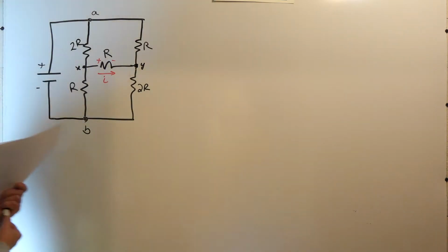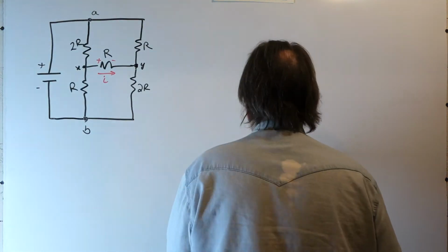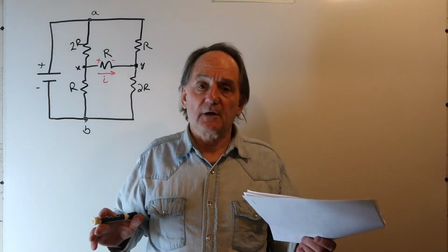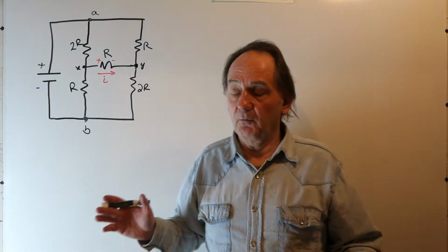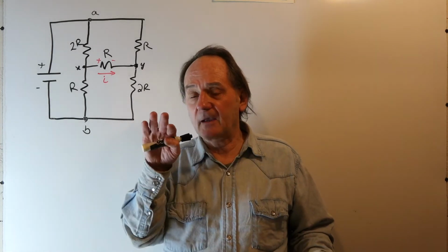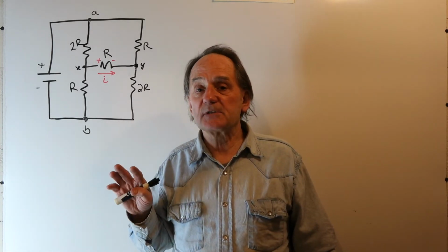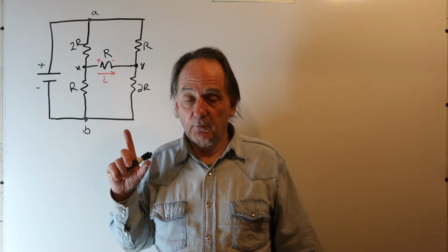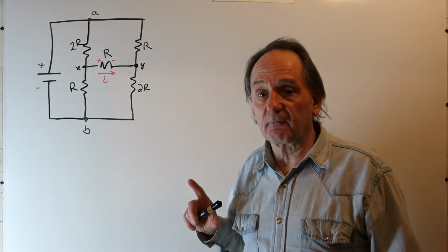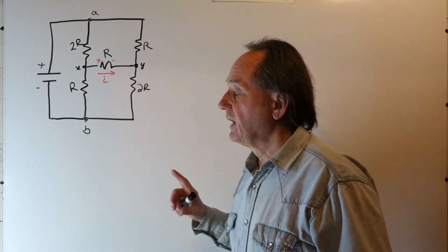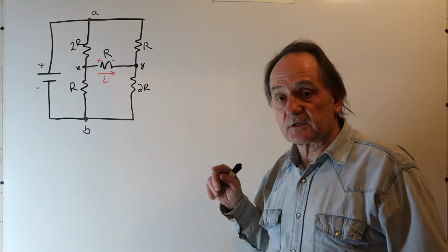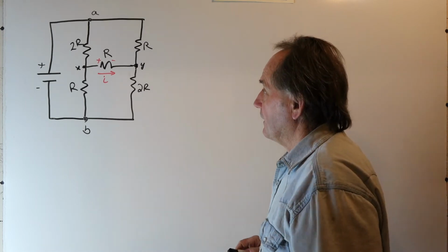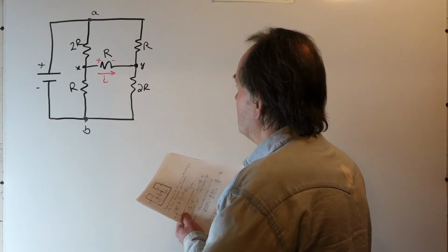Now, a Thevenin equivalent tells us that if I break the circuit at any point in the network, no matter how complex, and I look back into the network, I can represent it with a single voltage source in series with a resistance. We call the voltage on that voltage source the Thevenin voltage, and the resistance looking back into the network the Thevenin resistance, or the Thevenin impedance.